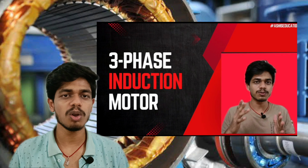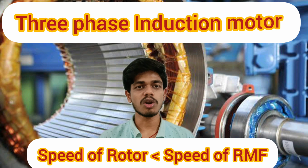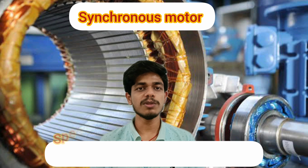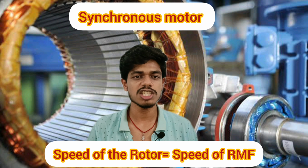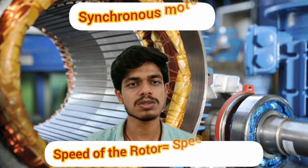But in the previous video we already discussed that in the induction motor the speed of the rotor is always less than the speed of the rotating magnetic field. But in the synchronous motor the speed of the rotating magnetic field and the speed of the rotor are equal to each other. As the speed of the rotor is equal to the speed of the rotating magnetic field, we call this motor a synchronous motor.